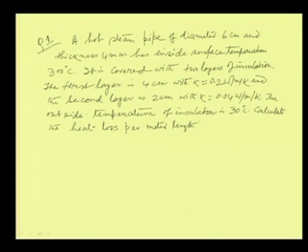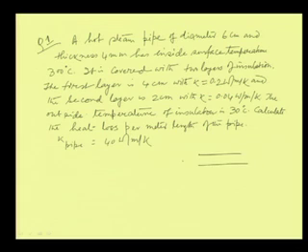Per meter length of the pipe. Now, the thermal conductivity of the pipe is very high, it is 40 watt per meter per Kelvin. Compared to the insulations, the thermal conductivity is very high. So, what we understand is that we have a steam pipe, this is the central line of the pipe, it has got a certain thickness. Then there are some insulations which are being applied, and that insulation is 4 centimeter thick.